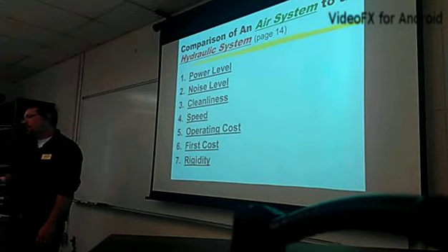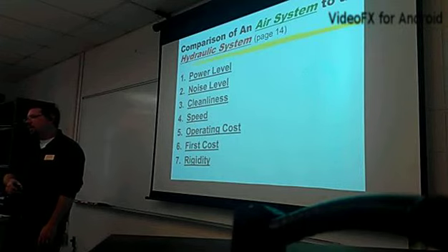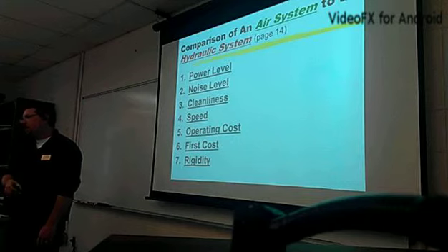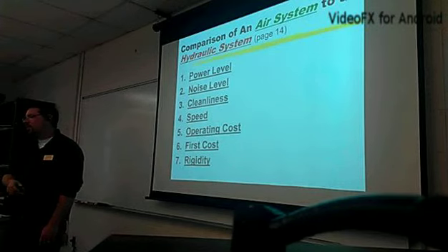All right, and if it's a large system, it's very inefficient to compress air and move it. In a large system, over years, we get little air leaks. And so what do we do? Our compressor works harder. And when it can't do it anymore, we buy another compressor. Now we're running 2 compressors. Why do we have to run 2 compressors? Well, because we have tiny little air leaks everywhere.